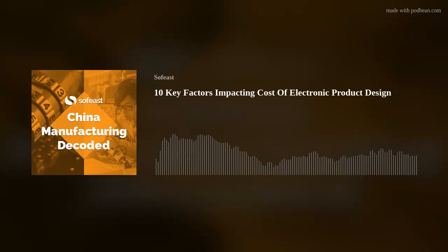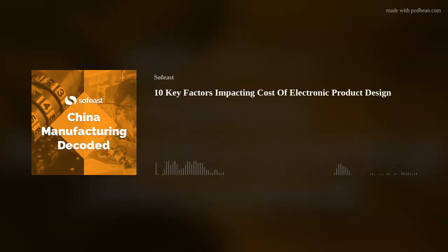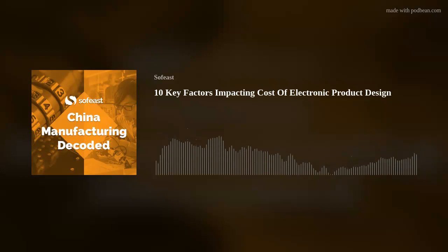And there are other things that we should mention here to our listeners, other processes such as poka-yoke and automation and simplifying the timing or time balancing of the line. They call it line balancing, actually. It's the same thing as time balancing. So you doing all of these all together, and for example, quality inspection in the line, all of these definitely helps lower the assembly cost.